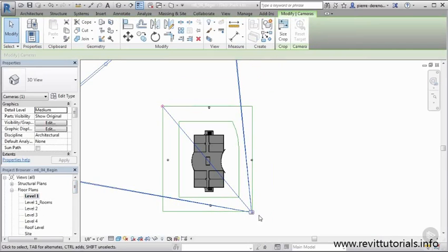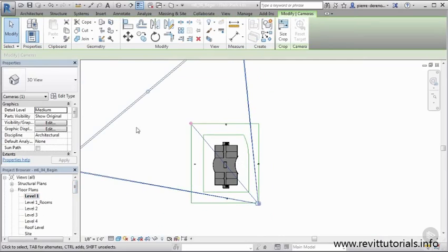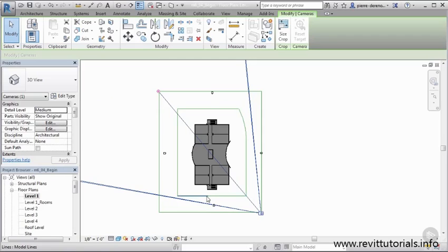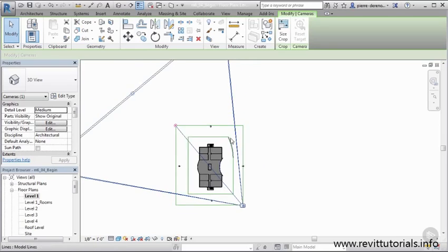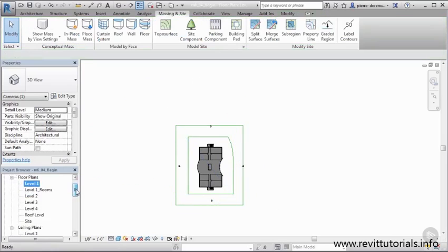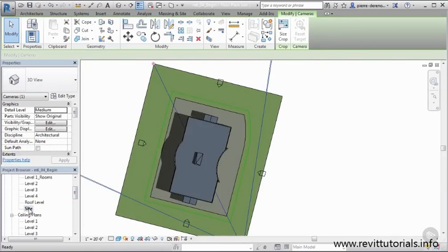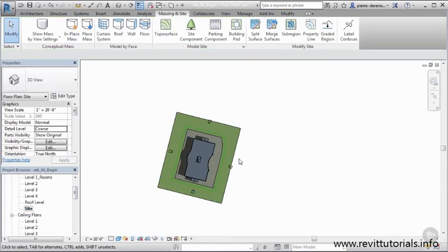I can see that I'm going to need to make sure that I place my entourage within this triangle. So that means my trees are going to need to come along this way, some along this way. And when I place my people, I want to make sure I place them all in here. They're all going to be included within the scope of this. So let's do that real quick. I'm going to go to Site. I'm going to hit Escape a couple of times to clear out that camera. And let's go to Massing and Site.